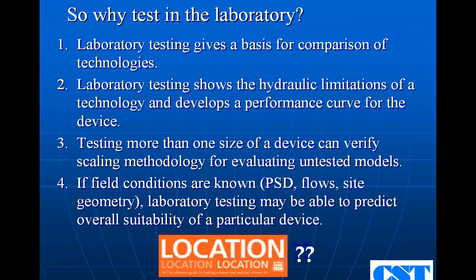If you test more than one size of your own device with similar geometry, you can verify a scaling methodology instead of just accepting surface loading or volumetric scaling. You can get a real scaling methodology. And by the way, that also changes by speed and some other things. So untested models can be projected. At least you've got 2 data points on the line. Really, you'd want to test 3 to start formulating a curve.